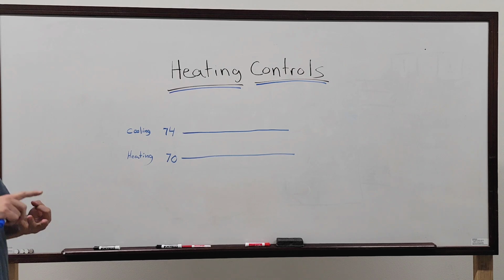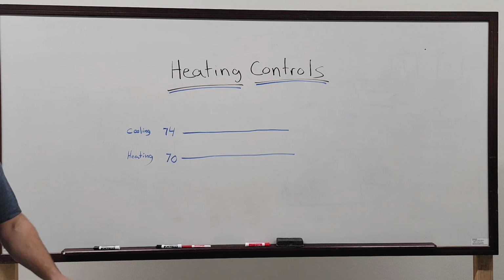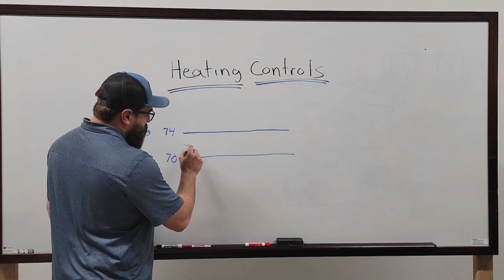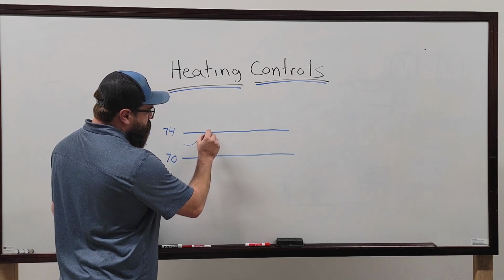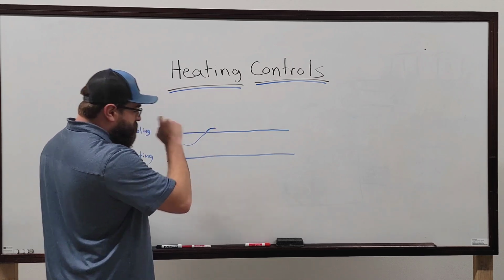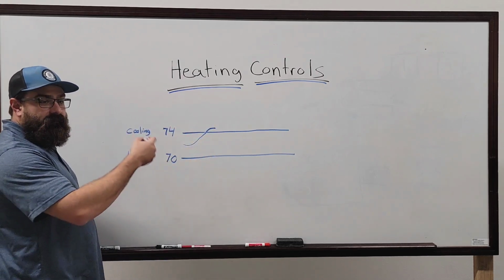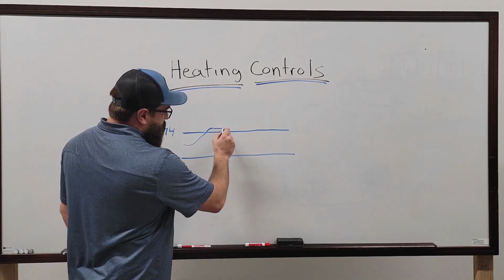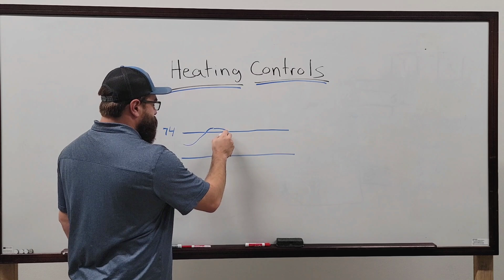Common, room set point, zone set point, like there's a bunch of different names. Different people call it different things. But think of it as temperature increases and gets closer to this, you would toggle into cooling, right? Which would then open up your air valve or start a compressor or whatever it may need to do. As it comes back down, oh, here, I'll touch on that real quick.